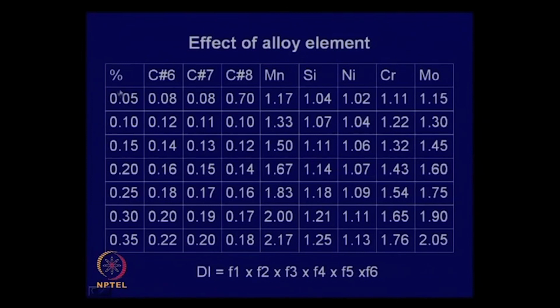At 0.5% carbon steel, the factor is 1.17, and there is a synergistic effect, as its effectiveness increases if the amount of carbon increases. With 0.35% manganese, that is the synergy. It need not necessarily be linear, but these are the values.